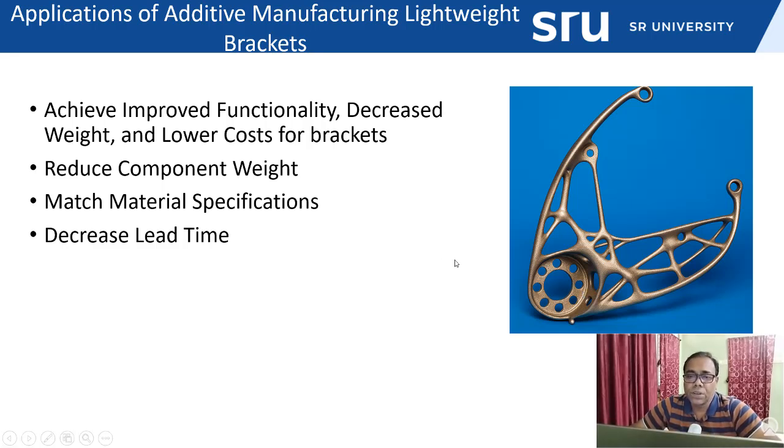intact itself. So here you have to achieve improved functionality, and it will have decreased weight and lower cost of the bracket. So these are the advantages. Similarly, it can reduce the component weight, because in the areas where the material requirement was not there, after doing the topology optimization, this area material will be removed. So topology optimization is very, very important for understanding those concepts itself. Similarly, it may match the material specification and decrease the lead time.